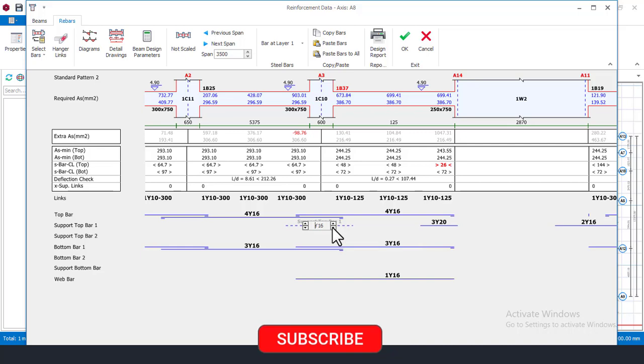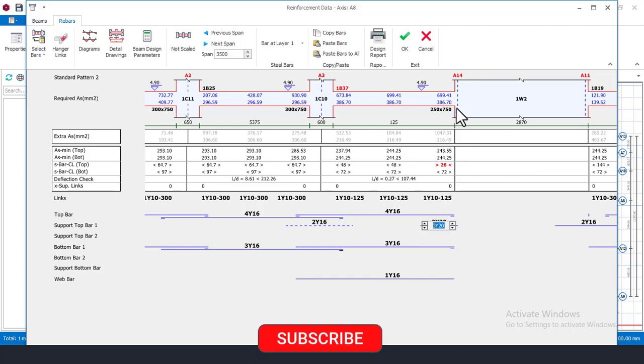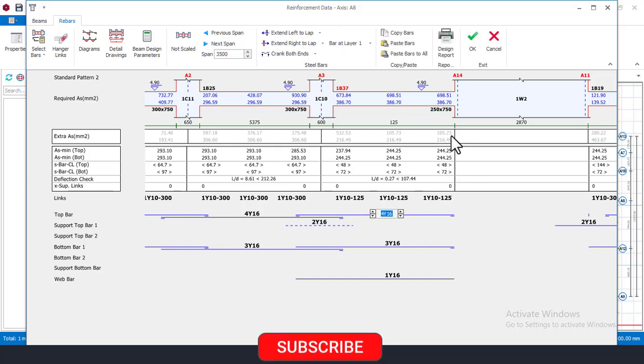I will use this right now and then add layer 2 at this support here, which is the supporting bars for the top bars at the support here. And I'll come here and make it to be 2. Okay, so right now we have 4 bars at layer 1 and then 2 just at the support here. Again, here right now, since there's a shear wall here, there's a wall here, you can see that this place we have much moment because of the contact between the beam, the wall and the beam. So I'll come here right now and then reduce this first to 16. Try to remove this entirely if that will be okay. Okay, that's fine. So this 4 was okay to carry that. You can see right there, there's no failure at the top here.